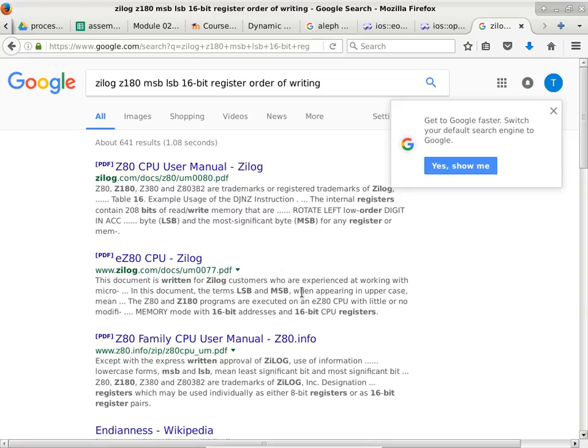So how is this problem going to show up as a problem when they change the die size? Okay, so at one point in time, Zilog changed the die size or changed the transistor technology. So Intel does it all the time, right? They change from 25 nanometer to 18 nanometer and so on and so forth. And Zilog did the same thing, except very much less frequently, but they did change. So the processor is still exactly the same processor, it will still be specified exactly the same way, but because the size of the transistors has changed, it also changed the race condition.